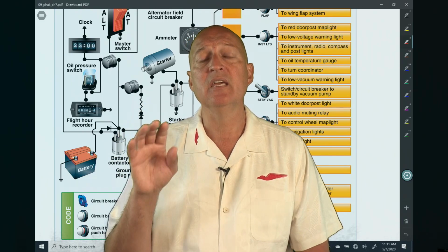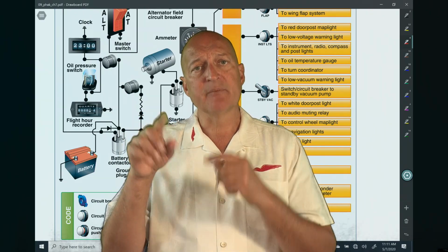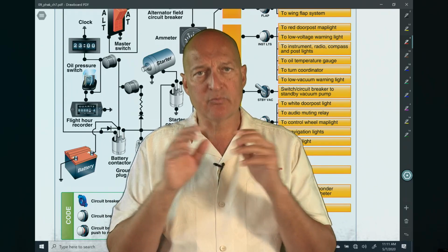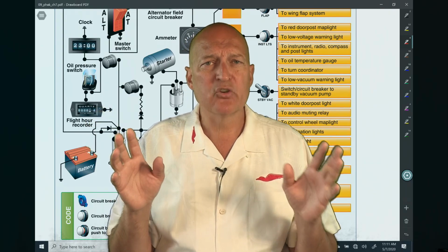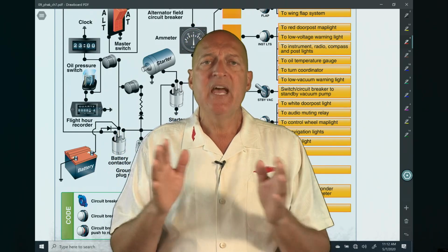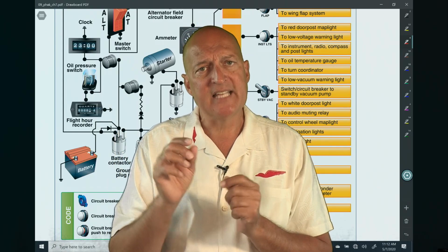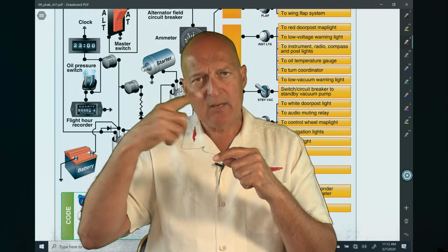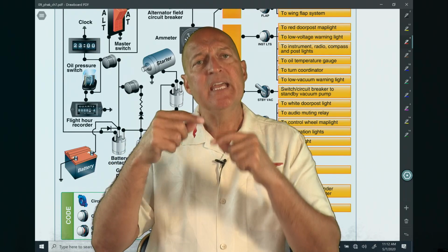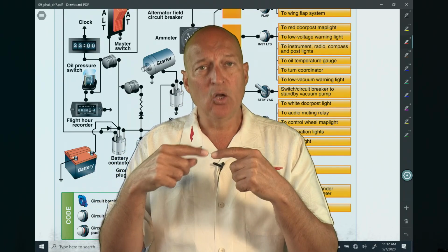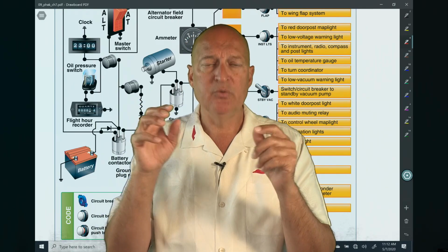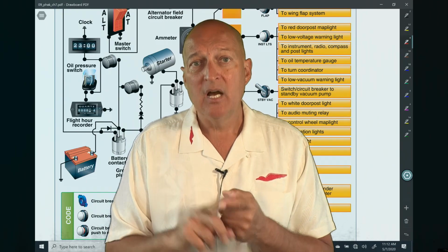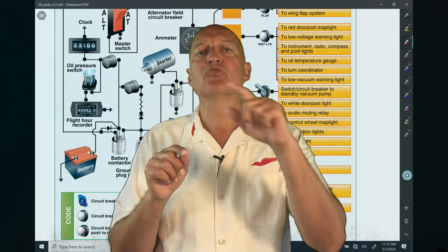When it comes to the alternator that supplies the electricity to the battery, everything runs through that battery to run through your systems, and it's sort of like your reservoir of electrons. That alternator is attached by a pulley system to your engine. So as the flywheel of your engine is spinning around, it will also turn that alternator. That alternator creates, through a system of diodes, electrical energy that is in the form of an alternating current into a direct current.